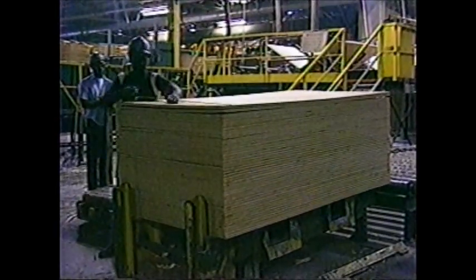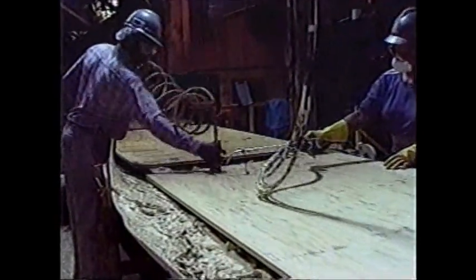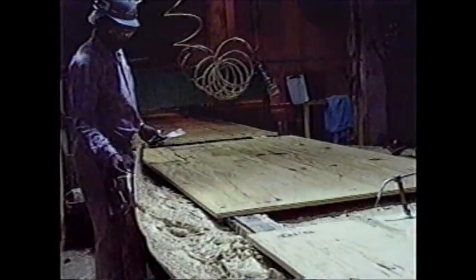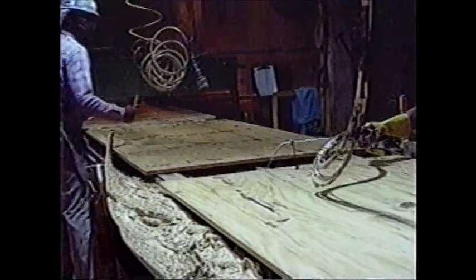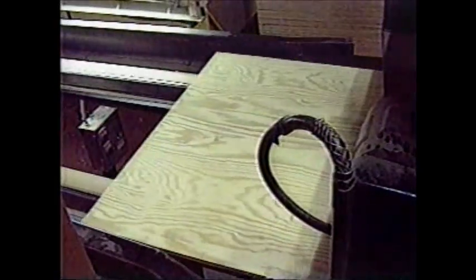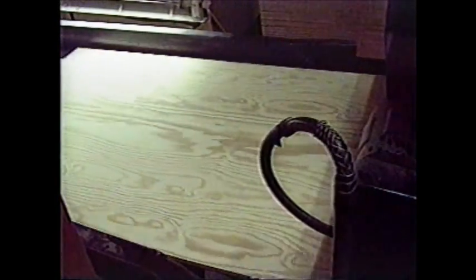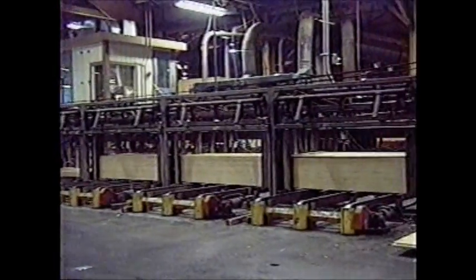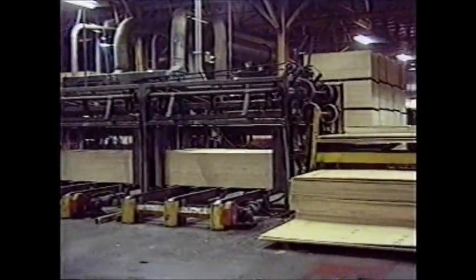As part of the grading process, certain panels which can be upgraded by patching with a synthetic material are identified. These are patched, the patch is cured by ultraviolet light, and the panels are then sanded to produce a high-quality surface. Sanded panels, usually higher quality, pass another grading station to be graded, grade marked, and sorted into appropriate stacks to be packaged and placed in inventory.